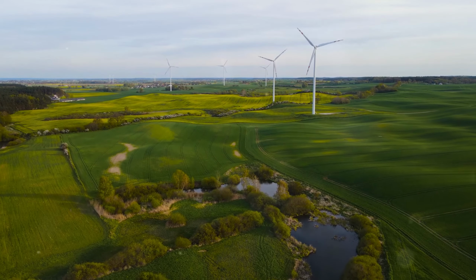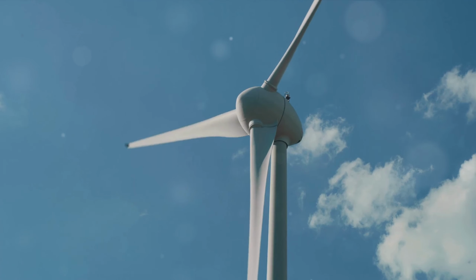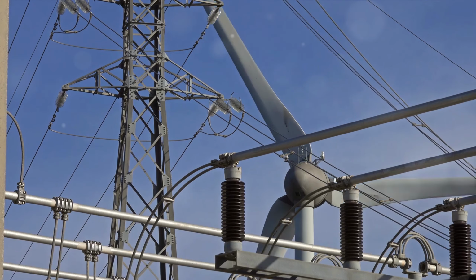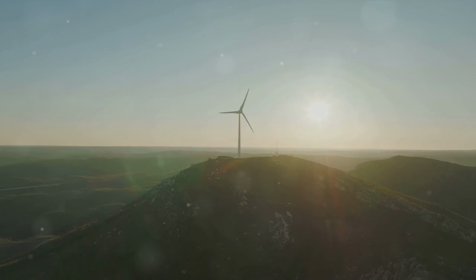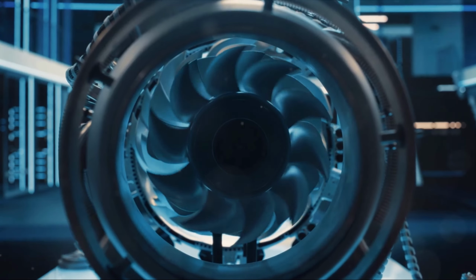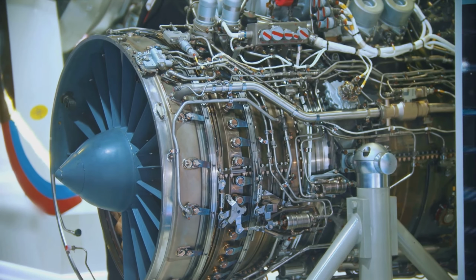On the other hand, the MRF model is a simplified, steady-state model used for simulating rotating parts. It's often applied in the design and analysis of pumps, fans, compressors, and other turbomachinery. The MRF model can help in predicting the performance of these machines under various operating conditions.